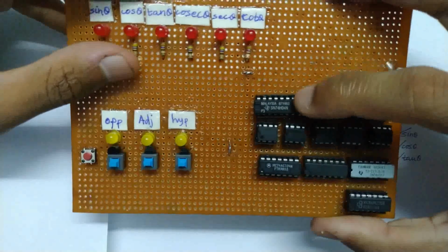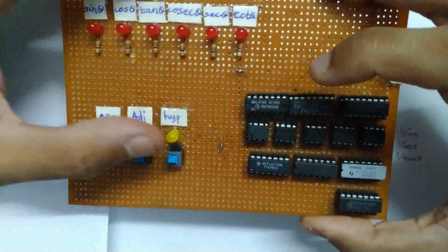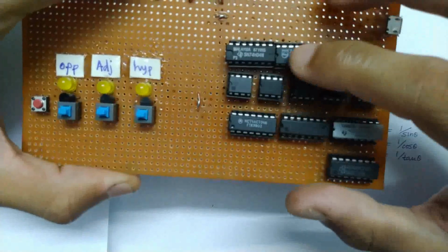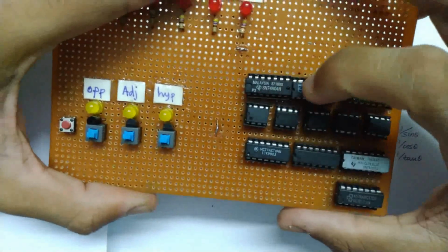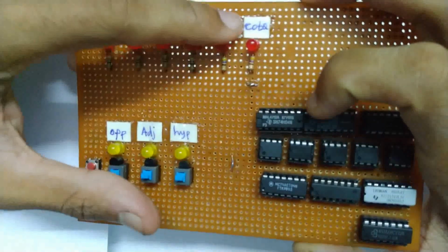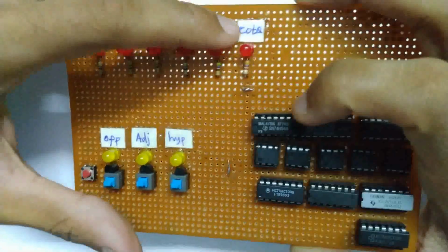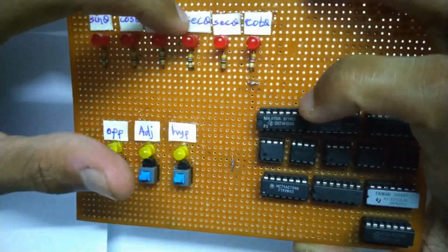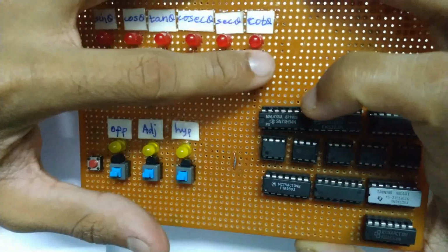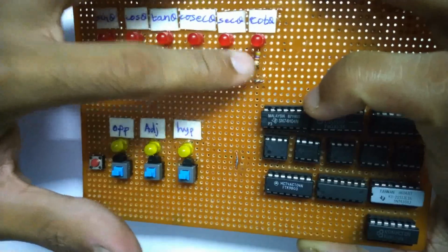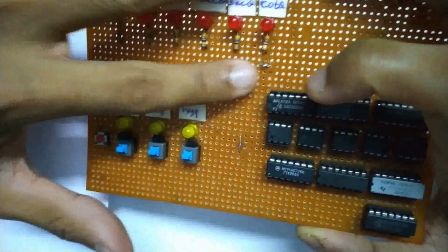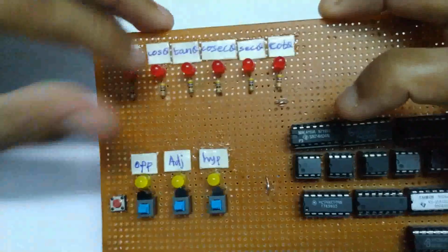So this decoder I've used to turn on these LEDs, and by clicking these buttons I'll be defining some binary values which will be ultimately given to this particular IC, and it will turn on that particular output, which will be useful to turn on these LEDs. The problem was that in a hurry I shorted all the cathodes of the LEDs, a general practice, and I took the anodes of the LEDs through these 470 ohm resistors. I kept this part of the circuit as it is.